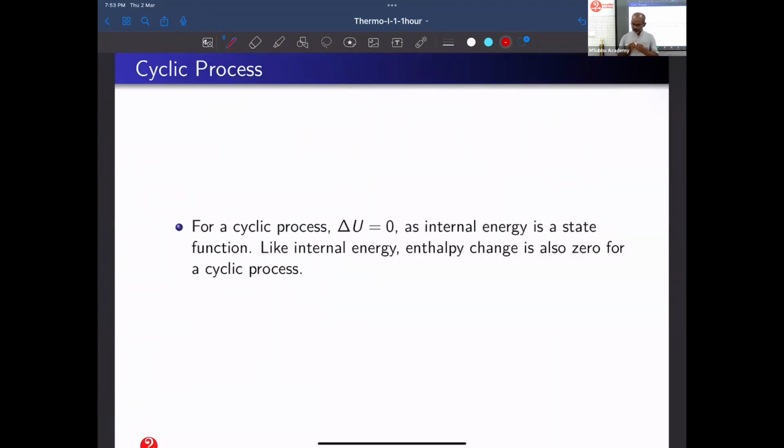And cyclic process. So what is going to be a cyclic process? Of course, there is a fluid which is undergoing changes and again coming back to the same state. This is very applicable for our boiler system. What is a power plant system? So there is water inflow. Water is going to the boiler, again going to the turbine, again going to the condenser and back to the boiler. So the water is in cyclic process, for which the total internal energy change of the water is simply 0. Not only internal energy change, it's also for any other energy quantities, of course, the enthalpy change is 0.